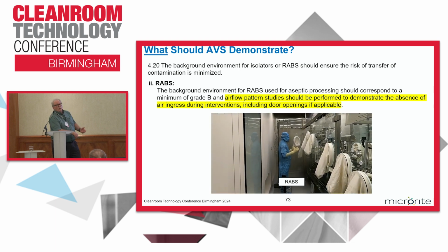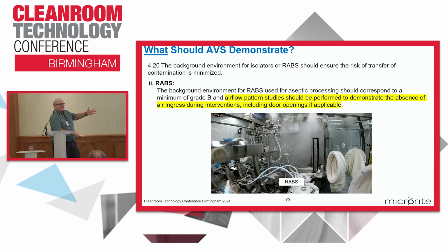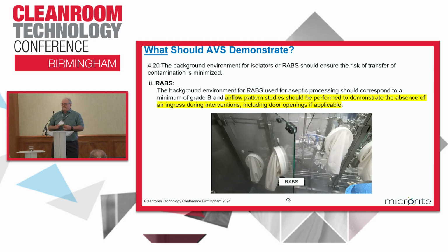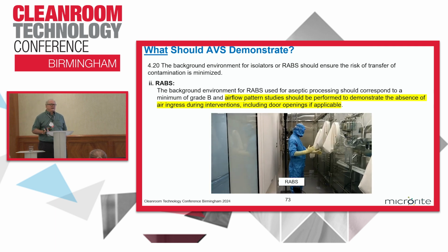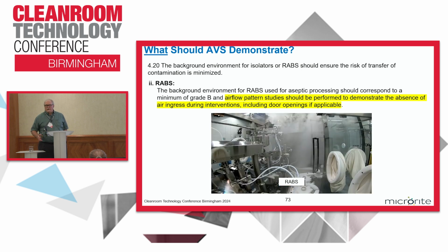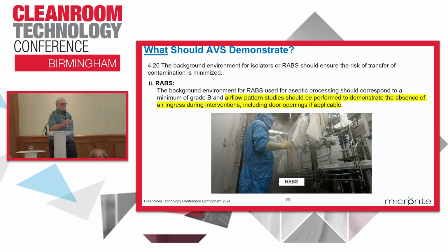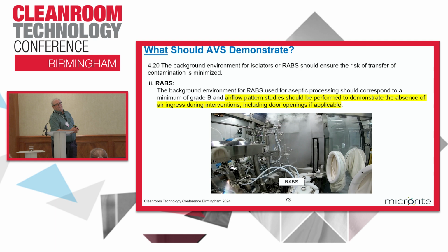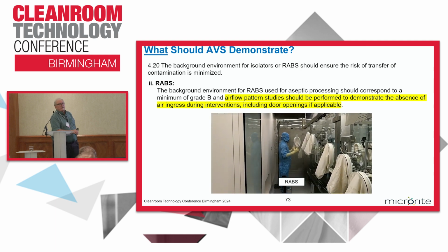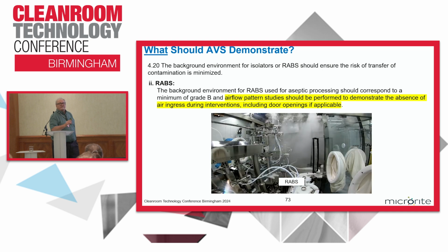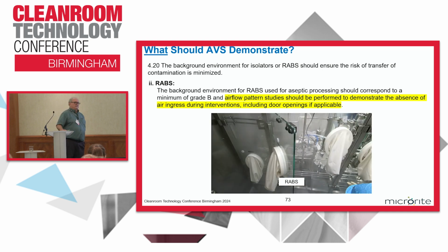Which brings me to another point when we talk about contamination control in general. Building leaks. Leaks of water in the interstitial when it rains is more common in pharmaceutical manufacturing than most people are aware of. It happens. It happens a lot. And one of the things I try to tell people when I teach a general course on contamination control is if you're making medical products and you have a building leak, a water leak in the building that you make medical products, you need to treat that as serious as a fire.